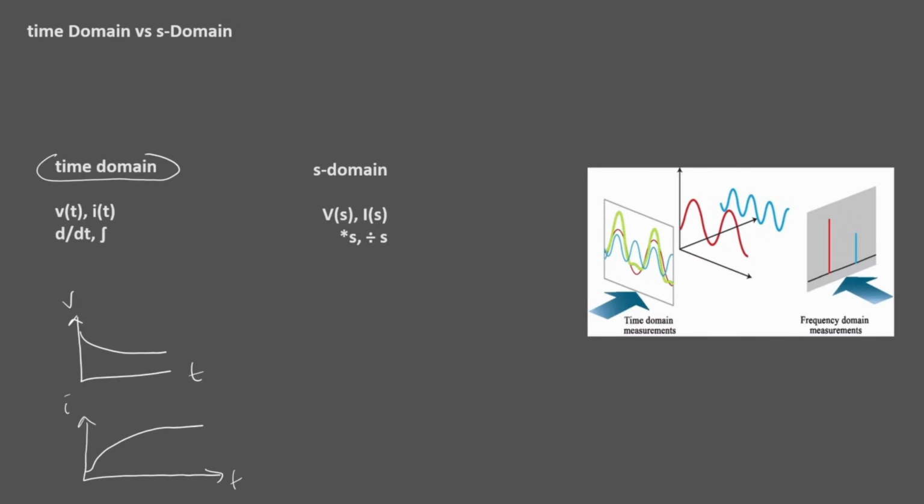These are the ways we are accustomed to analyzing circuits over time, with time as our variable. So you have V as a function of t, you have I as a function of t, and then you deal with differentials here, because for capacitor current, I of c is c dv/dt, all right, and inductor voltage is L di/dt. So since you're analyzing in the time domain, we become used to dealing with derivatives of voltage and of time. But what happens when you come over to the S domain is that all this becomes algebra.